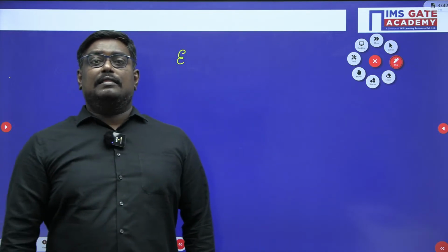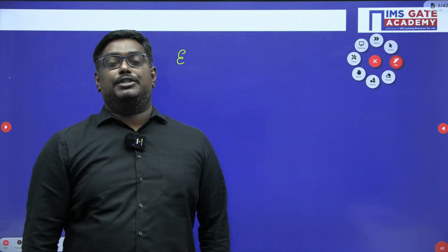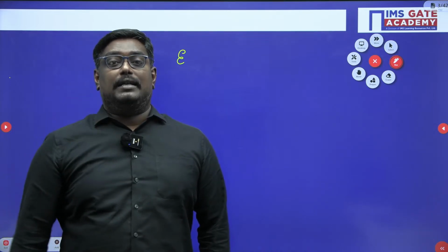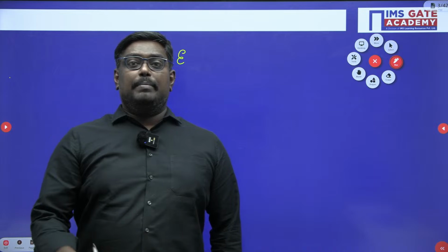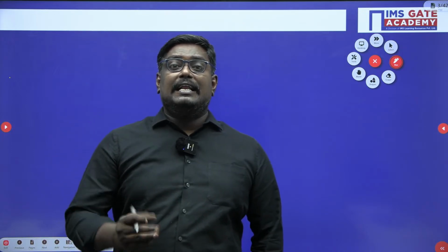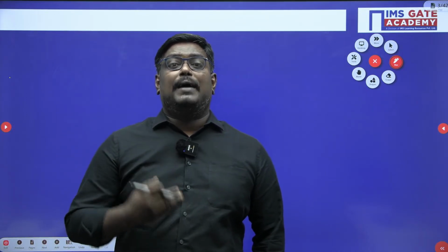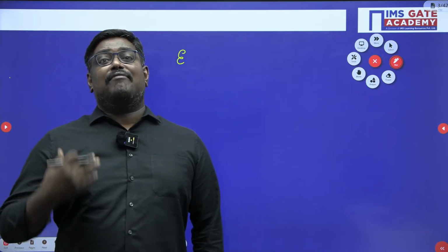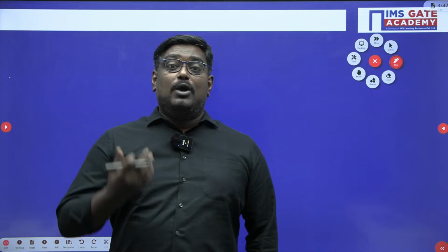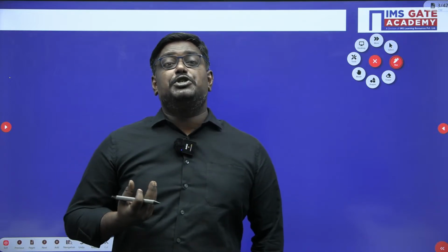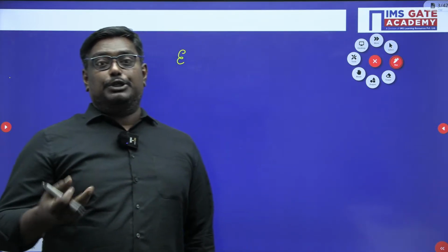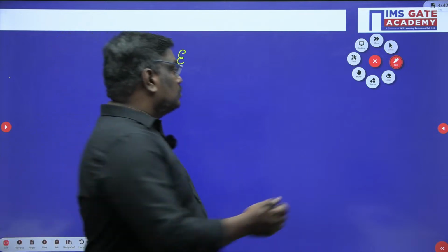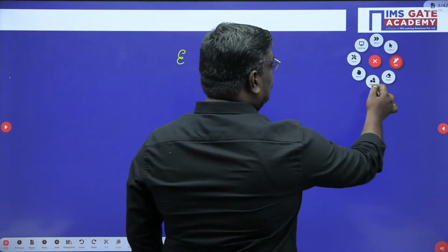Effective stress is nothing but the intergranular pressure between the soil particles. Now, why is the stress known as effective stress? Because it has an influence on the engineering properties like void ratio, shear strength and all. So, let us discuss that, students.